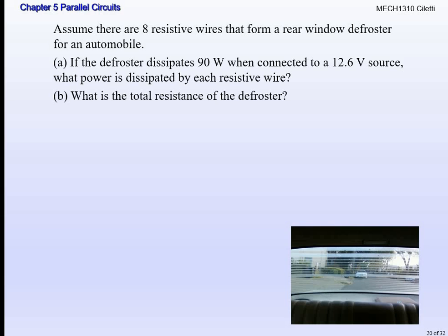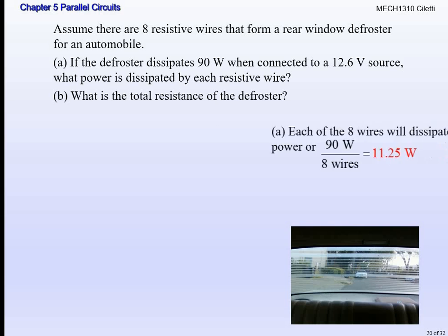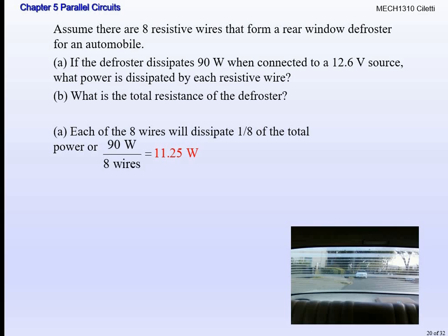We're solving for R. So you have to rework Watt's law just a little bit to solve for it. So P, all right, so P equals what? V squared over R, where R equals what? The V squared over P.